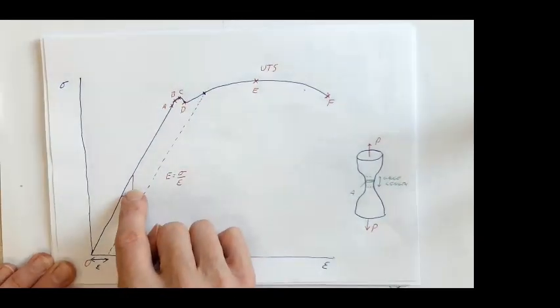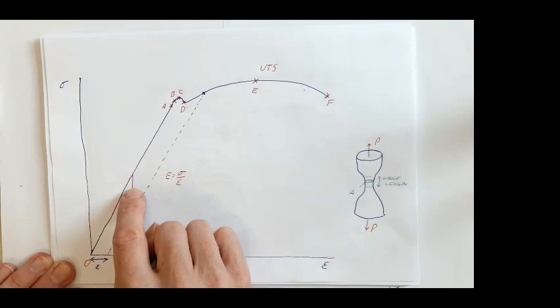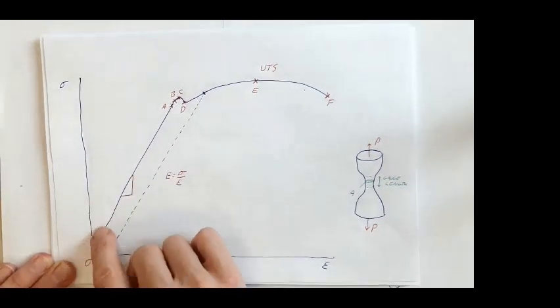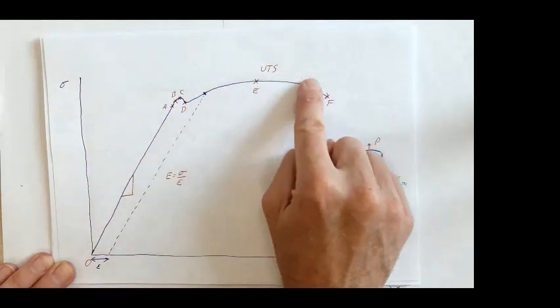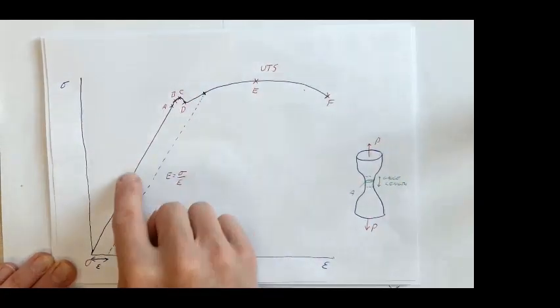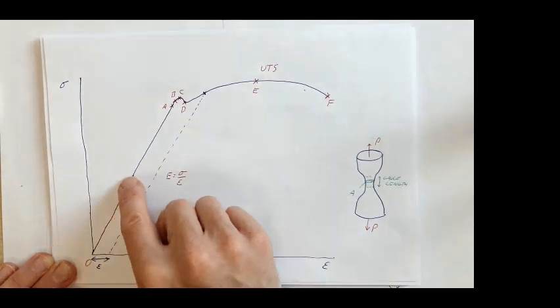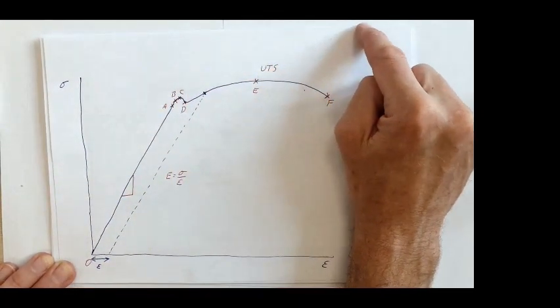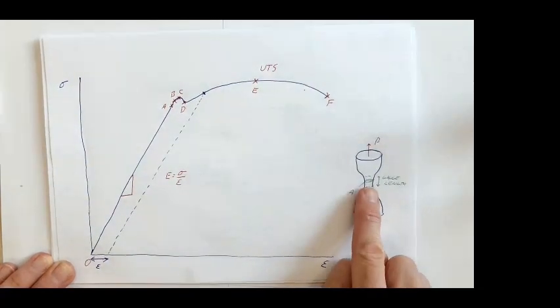We also understand how we would get our Young's modulus from our stress strain curve. And also we need to think about the fact that this is engineering stress strain that we're looking at here. Our true stress strain curve would head up here because we're seeing this area reducing. So therefore our stress is going to increase.